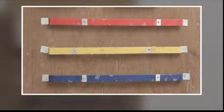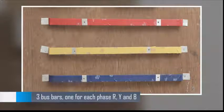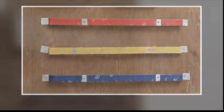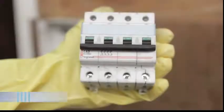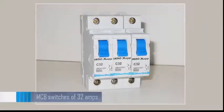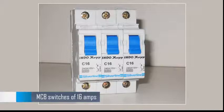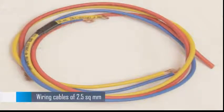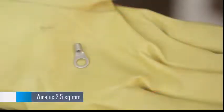For making a 3-phase distribution box, we will need the following components. 3 bus bars, 1 for each phase, R, Y and B. MCB box, TPN switch, MCB switches of 32 amps, MCB switches of 16 amps, wiring cables of 2.5 square mm, 2.5 square mm wire lugs.